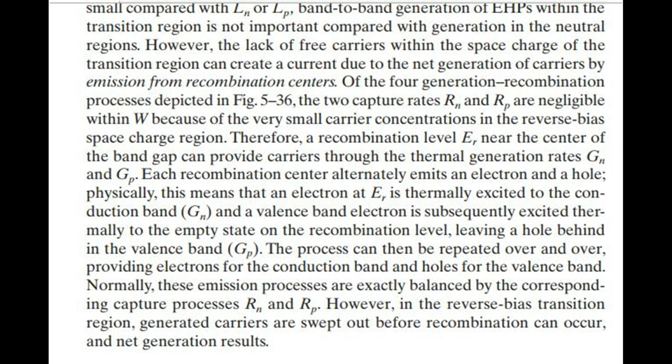Each recombination center alternately emits an electron and a hole. Physically, this means that an electron at E_R is thermally excited to the conduction band, Gn, and a valence band electron is subsequently excited thermally to the empty state on the recombination level, leaving a hole behind in the valence band,